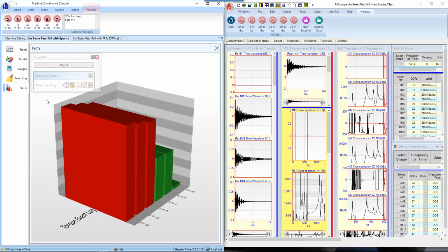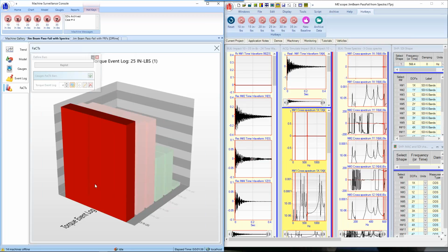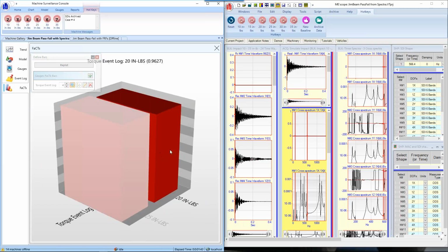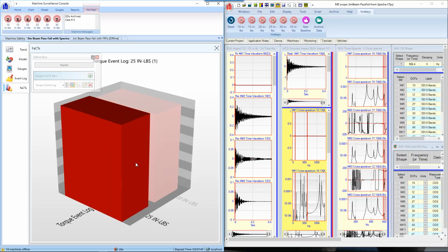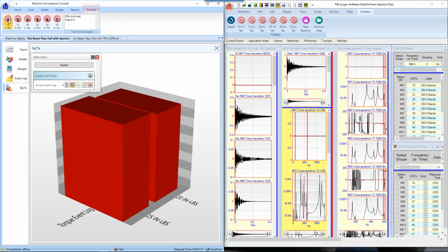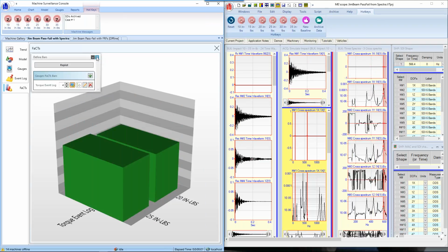And let's go back to Fax, and let me see what Fax is actually going to use out of the database. Okay, it's going to use all of the SDI values for the 6 bands. And remember, there's 3 measurements, so 6 times 3, there's 18 values here that it's going to match up out of the database. So there's a case where it's 25 inch-pounds matched up, and the second case there is 20. Let me go push 10 inch-pounds and see what, bingo, see there's a failure.